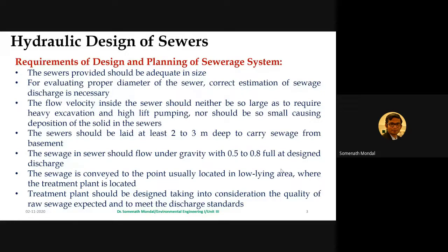And while talking about the less velocity, if the sewer velocity is less than a certain value, then all the solids, these are basically liquid and sometimes semi-solid which is moving through the sewers, will, if it is less than that, get deposited at the bottom, and they will not be able to move or roll down to the lower points, and thereby with respect to time you will end up reducing the diameter of the sewers.